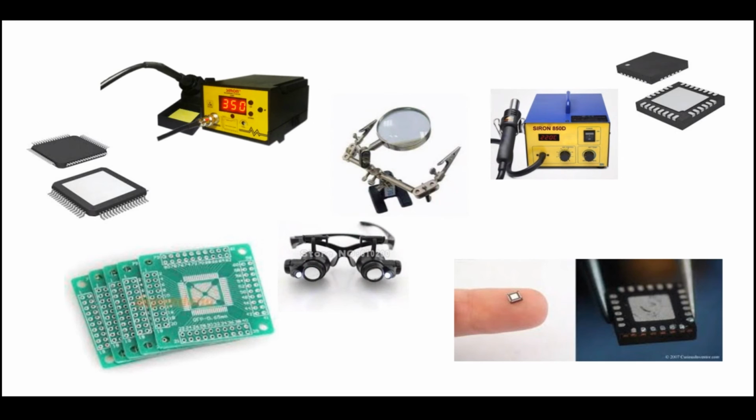And definitely one piece of advice is to go for a very high-end soldering iron, preferably with digital temperature control, where you would have better control of the temperature. And again, you would also have chips like this where you don't have the pins stretching out.